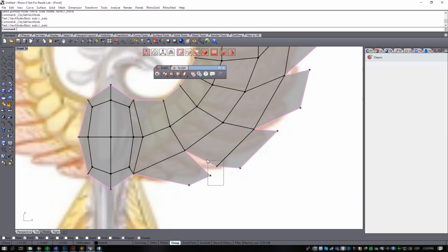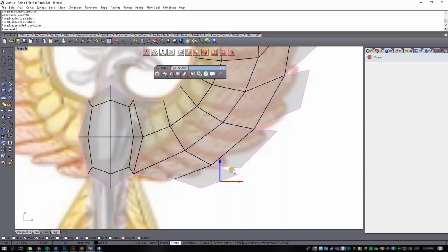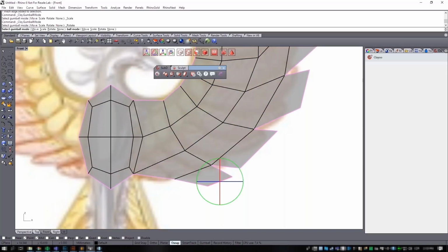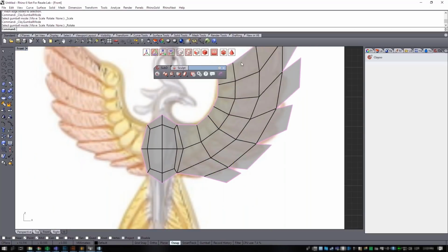We can anytime select these both vertex, and from here we can just weld these two vertex and merge it together. So right now I can refine that a little bit more, and we can just click 2 to select the edges, select the edge, hold Shift, hold Alt, sorry, and just refine a little bit this shape.